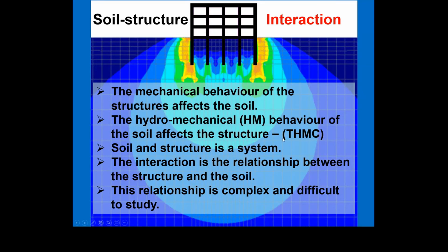Actually, if we do a more complex analysis in soils, you have to take into consideration the temperature, as I said before, and the chemicals that affect the soil in some way. So there are analyses called thermo-hydromechanical chemical analysis. We are not going to deal with that, don't worry. We are going to deal only with hydromechanical analysis because this is the minimum we need in our cases.